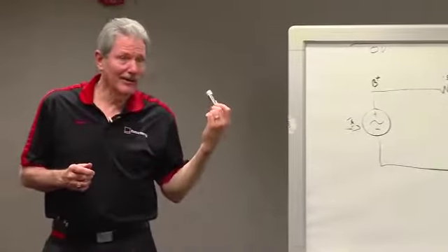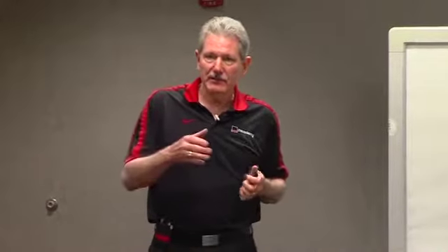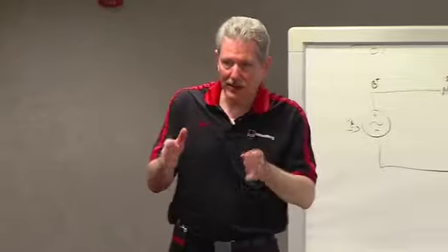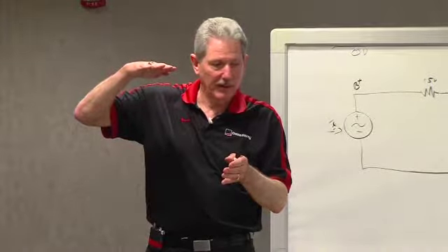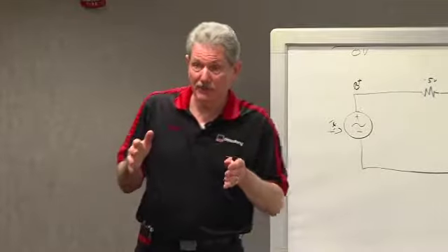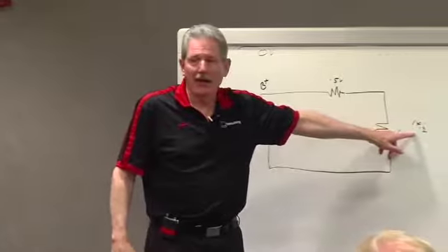And what I said earlier, that's not optimum, and it takes longer to charge. So if you've got a vehicle that's doing a lot of stops and starts, a delivery vehicle, you'll have what's called discharge at idle. Your vehicle at the end of the day will discharge because I've lost a half a volt here.